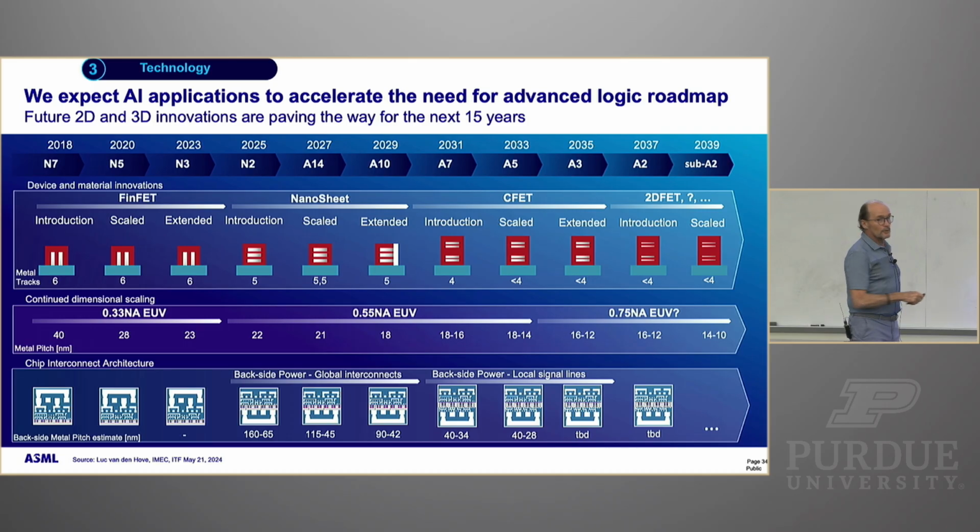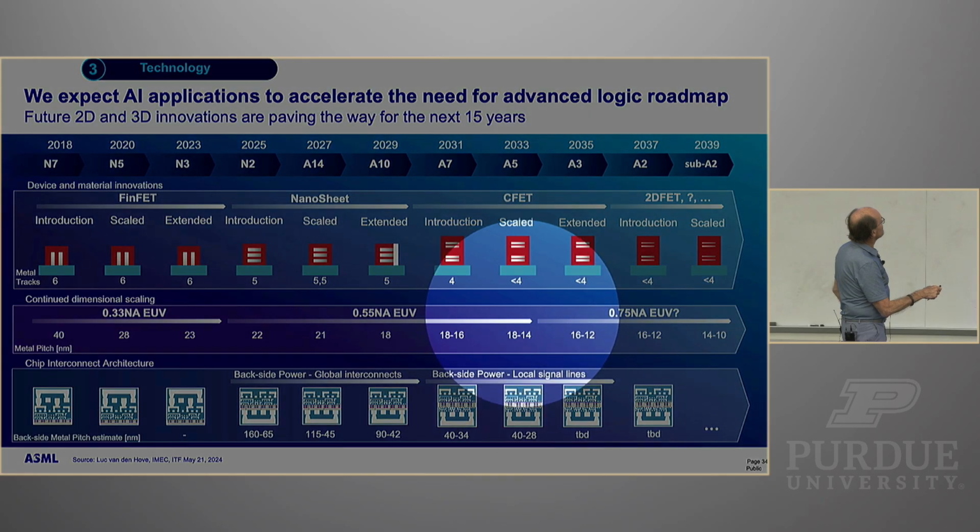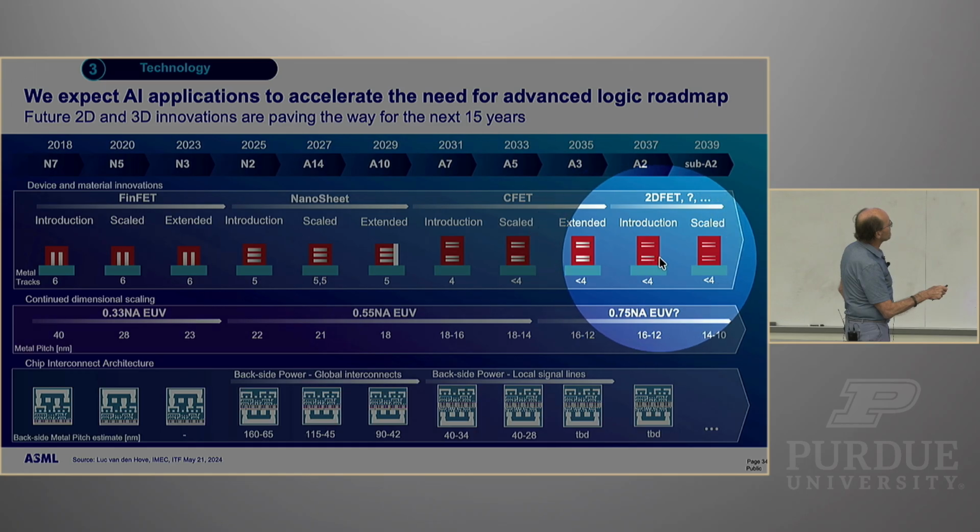And if I want even lower voltage, because we were also talking about power, we wanted the power to be lower, so I want all the voltages to be lower. The switching power is something like V squared R, right? So if I can halve the voltage, I only need a quarter of the power. But then it becomes even more important to be able to turn it off, because now I have so little voltage change between the gate voltage being on or off. So that's when we say, can we make these nanosheets and these CFETs, can't we make them thinner?